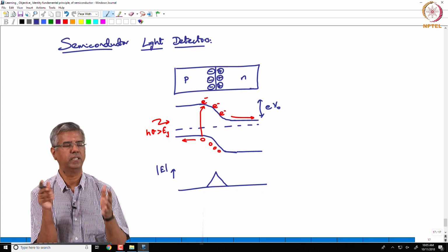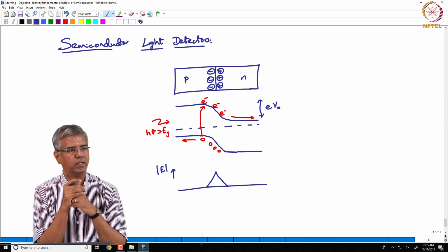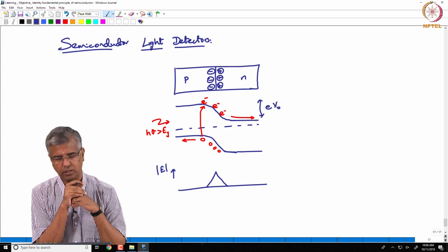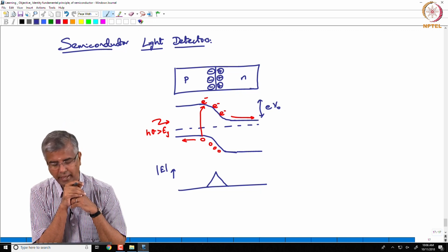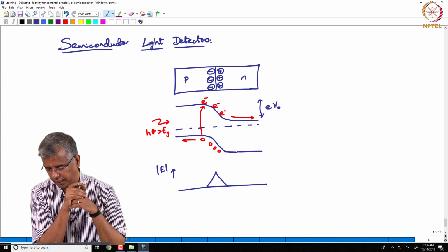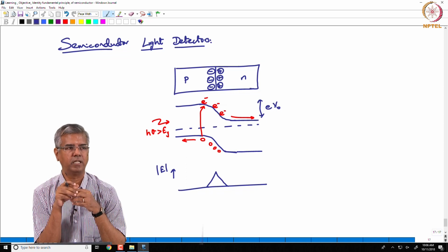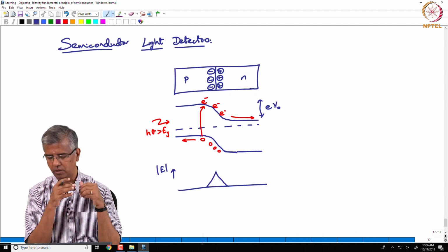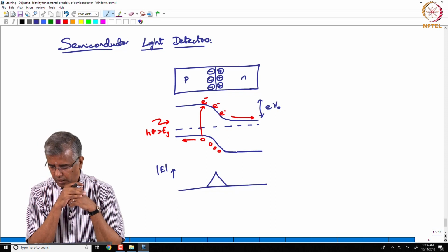Without any external illumination, it is all at equilibrium. So, there is no transfer of charges across that barrier, right. But in the presence of light, when light actually falls on this photodiode, it generates electron hole pairs, and then those electron hole pairs, the inbuilt electric field actually ends up pushing those electrons to the right side and holes to the left side. Okay.